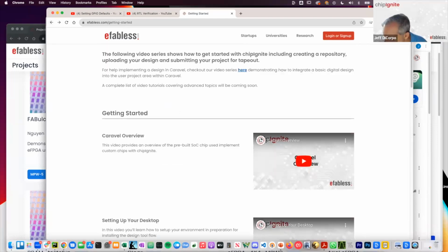Does the user project implement the Wishbone slave port logic, or directly connect register SRAM ports? Does the user project have to implement the Wishbone? You're not required to implement a Wishbone slave port, but obviously that's an option and a useful one if you want to be able to connect to registers within your design.